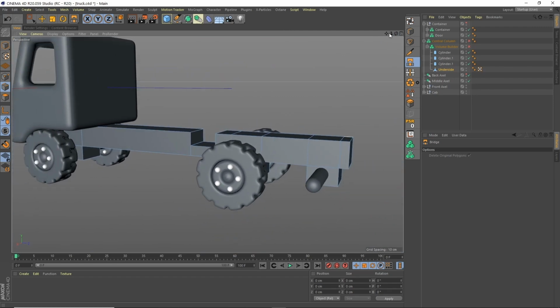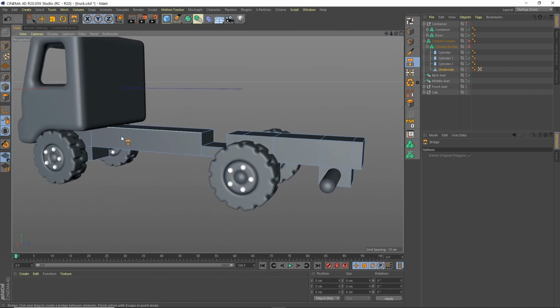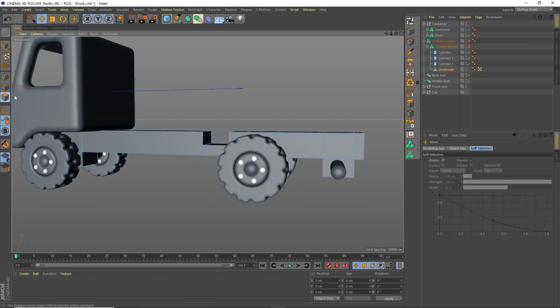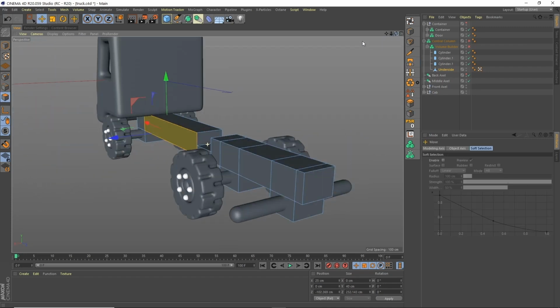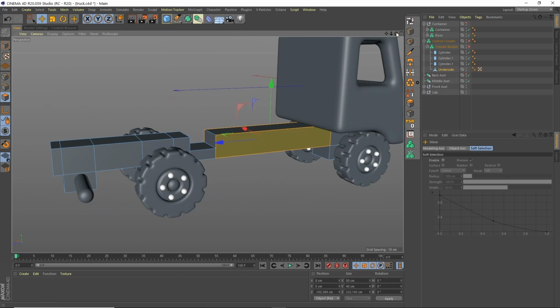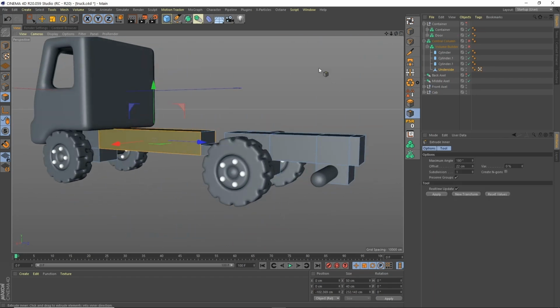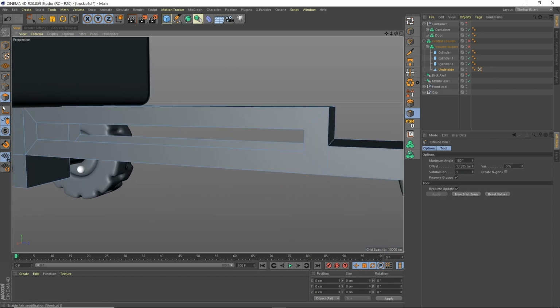Now, the other thing I want to do is have this object that kind of lifts up the back. It needs to slide along something. So we need to kind of cut a hole out the middle here. So I think I'm going to select both sides here. Extrude these in. Something like that. Delete those. Just going to link these up.